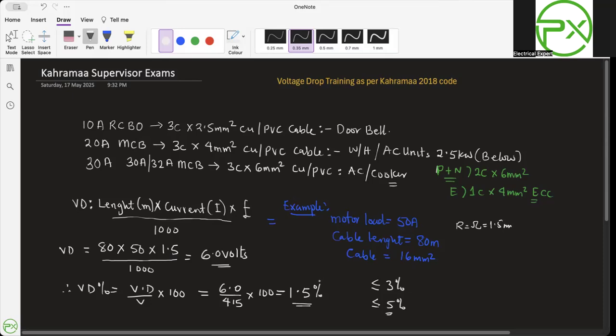And then also, if I increase the size of my cable, for example, if 16 mm square cable is required for the installation, and I'm calculating my voltage drop and it is more than 3% or 5%, then I just move to the next size of cable, which is 25 mm square, and the voltage drop reduces immediately. So it's quite important in designing or in installation for us to calculate voltage drop first before we start the execution. I have to stop here because I don't want it to be more lengthy, and for me to be able to upload it on the system.